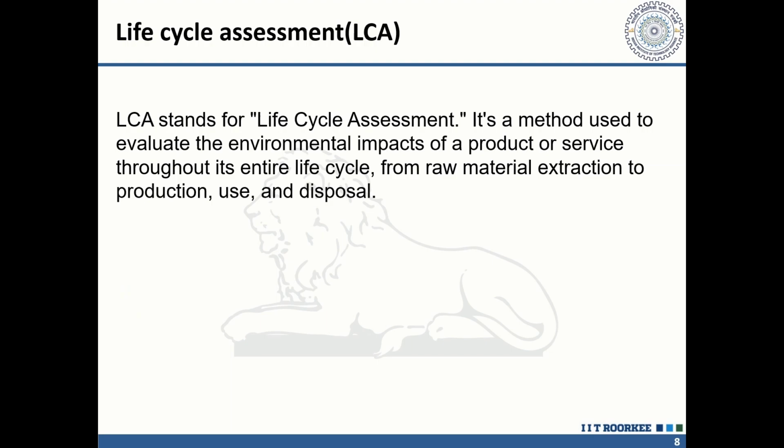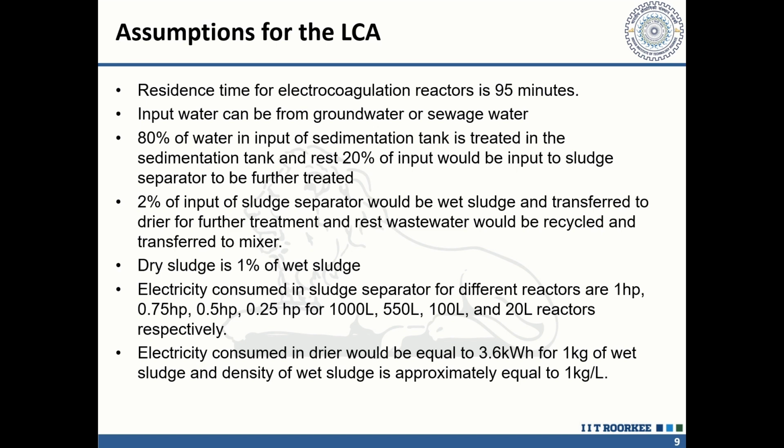Thank you. Hello, I'm Sundram. Let us see what life cycle assessment is. LCA is mainly used to compare 2 processes, to see which one is better for our environment. For the LCA assumptions, we have taken a residence time of 95 minutes, and electricity consumed in the sludge separator for the different reactors as 1 HP, and electricity consumed in the dryer would be equal to 3.6 kW for 1 kg of wet sludge.